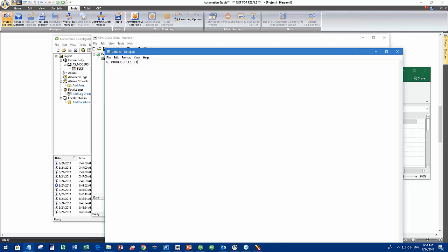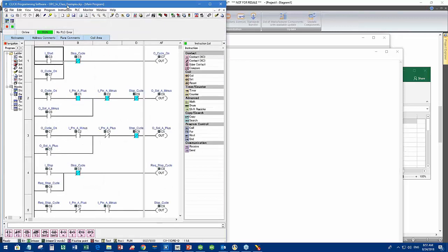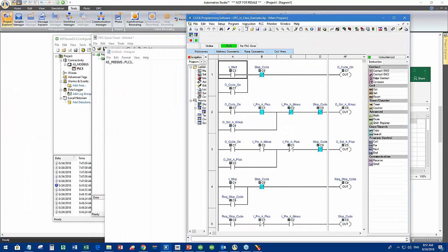But because it's not there, and I said it's a Modbus device, I have to write here the equivalent address in Modbus for C1. So this part, I don't have to worry much about it because the manual of the PLC gave it to me. So in my case, I can find it over here with this interface.